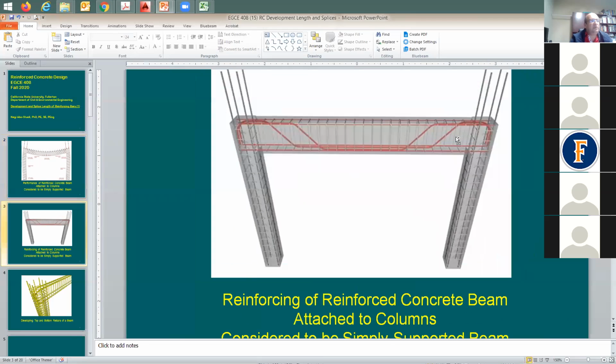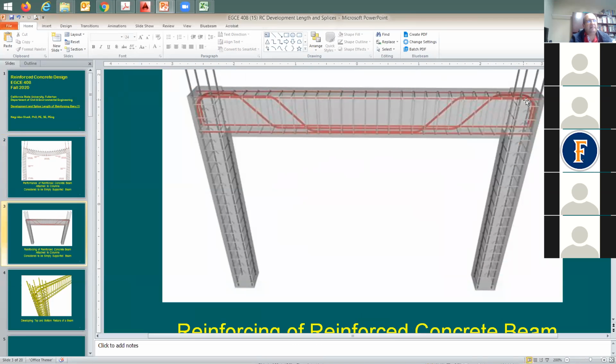Now let me show you here what we do. Here's the end of the rebar, right? So in this case, we need to bring it down. The reason that we're going to bring it down, we are going to hook it this way. We call this, just so you guys know, a 90-degree standard hook. So the reason that we do this is to be able to develop the bar. So what does it mean to develop the bar? Developing the bar means, in order for you to gain the strength that you designed for, you need to be sure that the force is really transferred to the concrete. If there is no development for the rebar, once you put this force on the rebar it's going to come out of the concrete. Does it make sense?